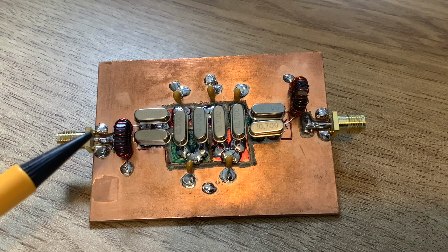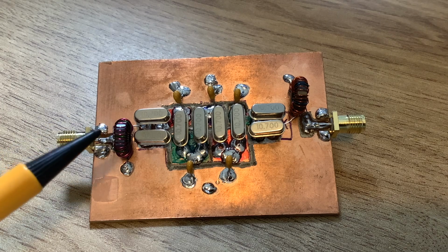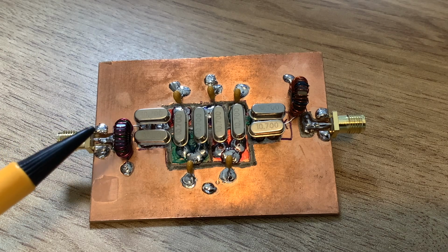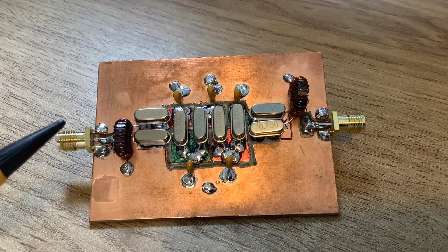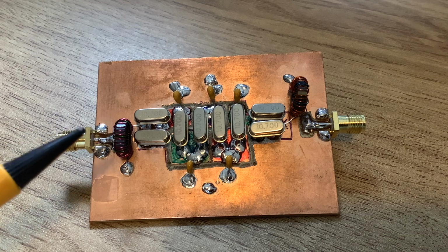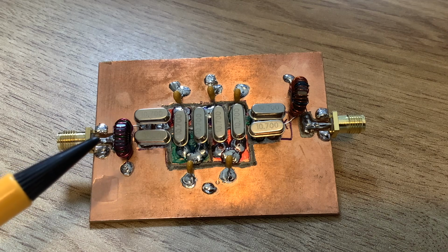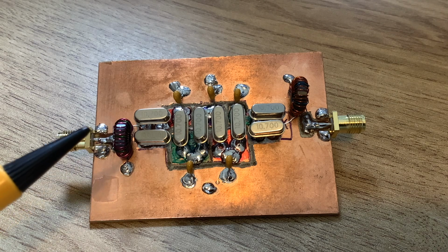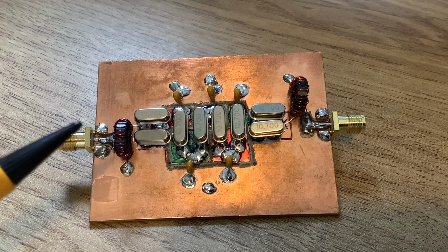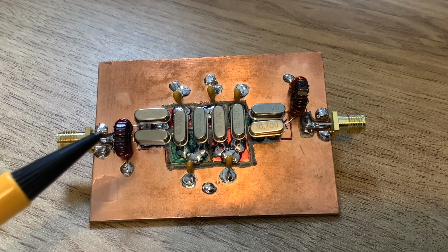So I need to be seeing 200, 250 ohms inductive reactance at least on the 50 ohms end. And at 10.7 megahertz, that means I need at least 3 turns. So I went one more than that. If I put 4 turns on the primary, that would mean 4 turns times the impedance matching ratio, which is 4.9, would give me 19.6. Well, of course, I can't have 19.6 turns, but let's call it 20. So that's what I went for.